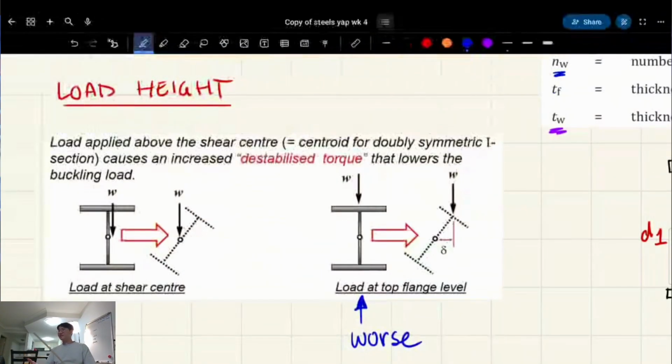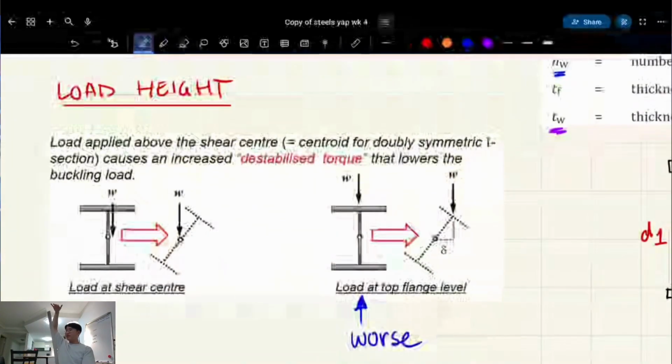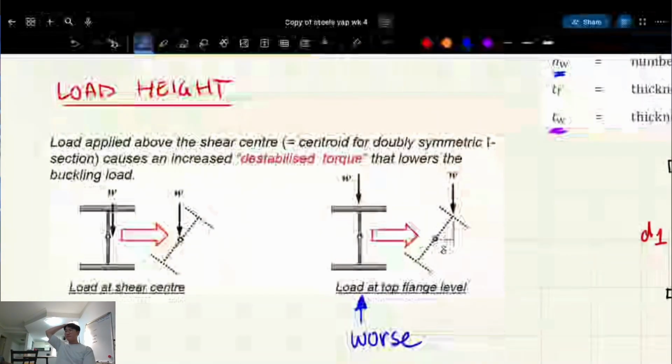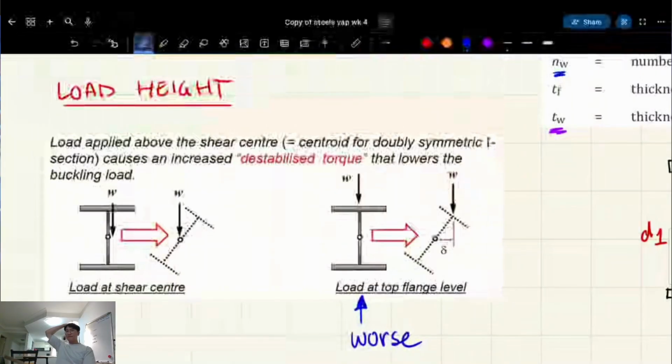These are suspended beams in the air, right? What about wind load? Wind load is probably more flange, because if you have wind that's pushing down or sucking up, it's going to be loaded at the flange. Oh, so that's bad. But this is for where? Shear center. Yeah, but top flange loading.